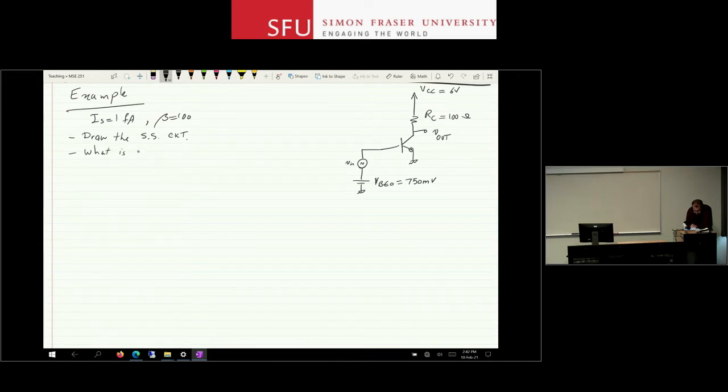And when I talk about voltage gain, it's only the small signal part, right? So if it is 2 volts DC plus 100 millivolts AC at the output, it's only 100 millivolts. The 2 volt DC is not included, right? What is the voltage gain?